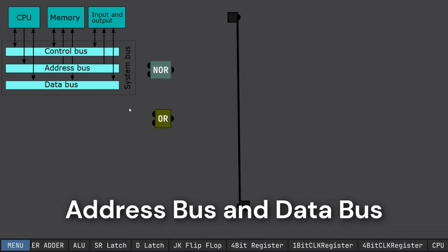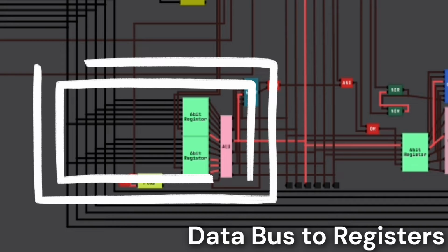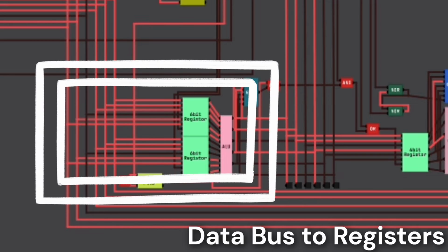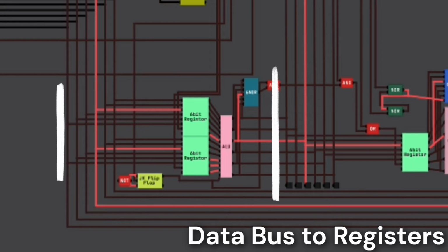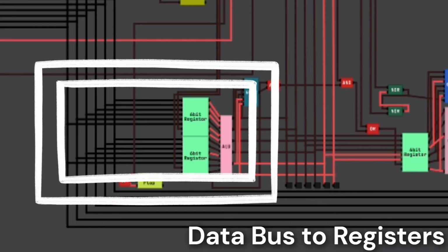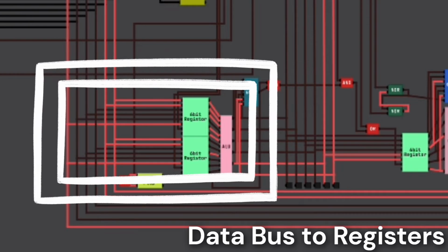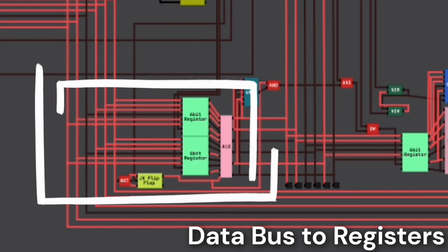So a data bus is just going to spit 4-bit data out onto electrical paths. We're going to have 4 of these electrical paths, each for 1 bit of data, and it's going to be primarily used by registers and the ALU. So the registers are going to input their data onto the bus, and then the ALU is going to receive the data and spit out new data for the registers to restore, all on either the same bus or 2 different buses or however many we need.